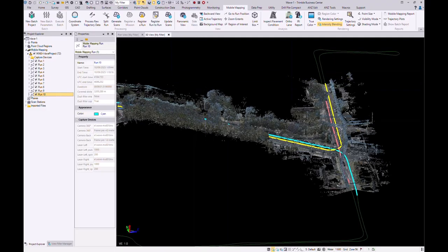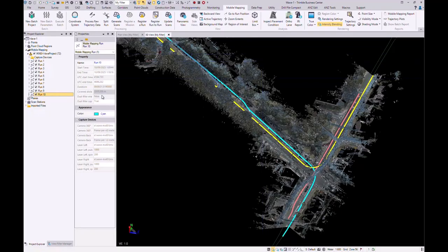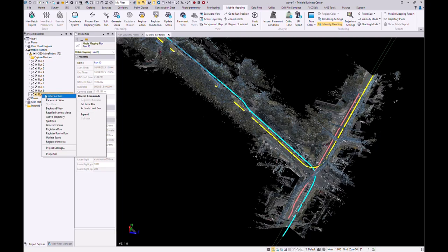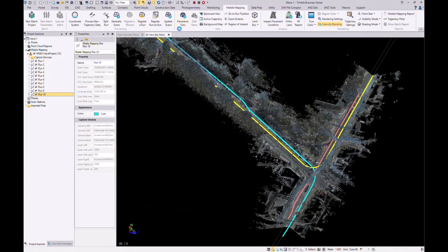From here, there's a few different viewing methods. So we've captured all this imagery as part of this runs. We want to use them. So if I wanted to select and view the panoramic image here, a lot of the options are actually available in the right click. So if you right click a particular run or mission, it'll give you all these options of tasks available. So I could select panoramic view here, or as mentioned, there's often multiple avenues to do that. So you can see up the top here, panoramic view. I could hit that, and that will open my 360 imagery.